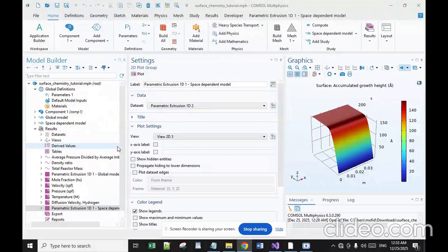And what are the applications? The first one is semiconductors, depositing insulators, conductors, and semiconductors for chips. The next one is optics, anti-reflective coating on lenses. The next application is energy, protective layers on solar cells or fuel cells. The next application is medical: biocompatible coating on implants, for example, hydroxyapatite. The next application is tools, for hard and wear resistant coating on cutting tools.